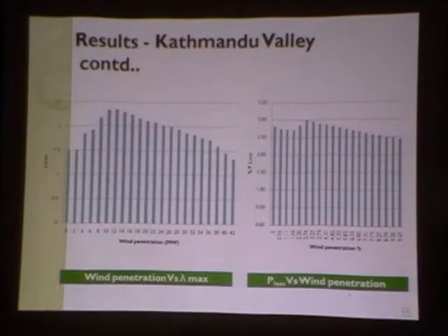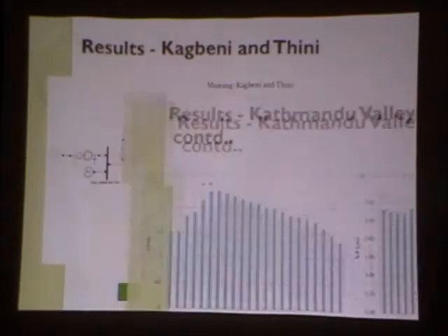And for that case, the loss tendency shows that within 3.27% of penetration, there is a certain increase in the loss. This is because of the maximum wind generation penetration near the highly loaded line. So that has to be considered during practical evaluation.